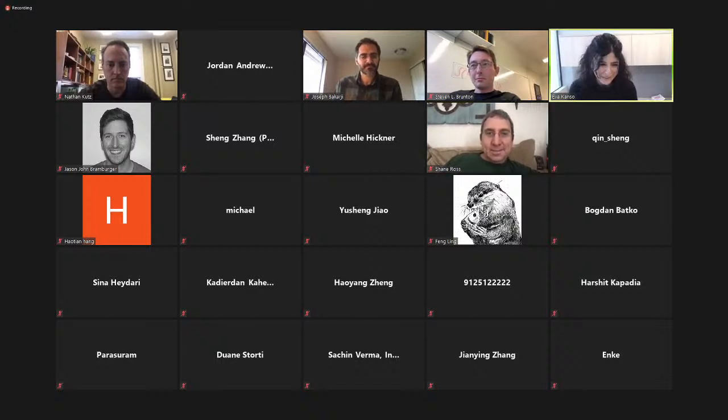So, Shane, we can use a completely deformable body for that type of study. The issue is always in the hydrodynamics. We still need to do 2D hydrodynamics if we are going to use those simplified reduced order models. The trade-off is that you want a reduced order model for the hydrodynamics, and it's mostly two-dimensional because we don't know how to do non-axisymmetric three-dimensional flows with those reduced order models.